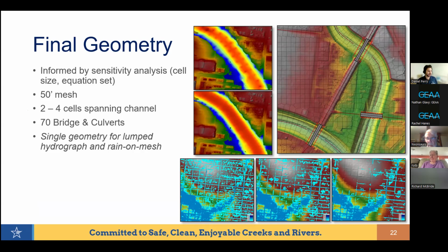The land is divided into a grid of small squares, as you can see in this image to the right here, and it's like a checkerboard. The model uses the grid along with the elevation data, which is what you can see below that grid, the green to red to white and gray, and rainfall data to simulate how the water flows. So we divided in this area. We did some sensitivity analysis from 200 by 200 to 50 by 50 grid cells, and we ended up choosing the 50 by 50 grid cell to give clear results, even with the longer runtime.